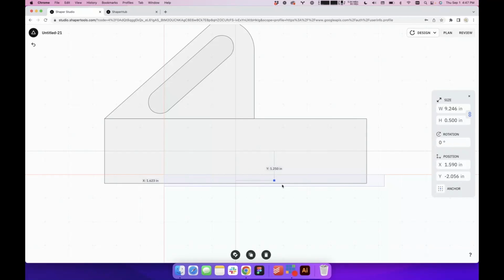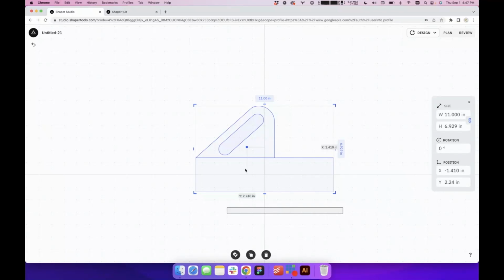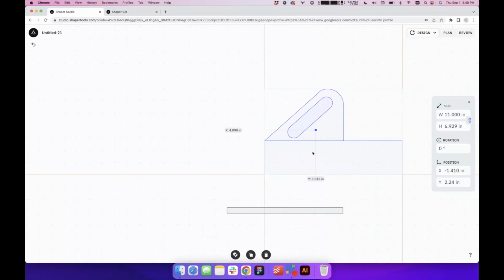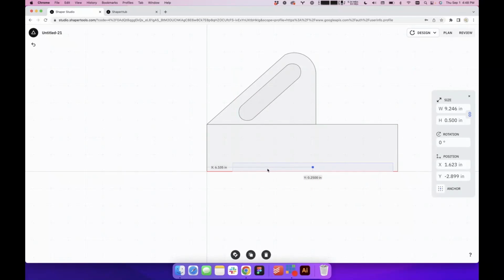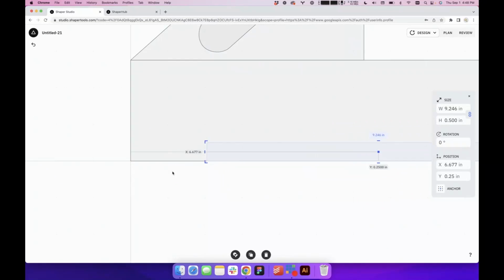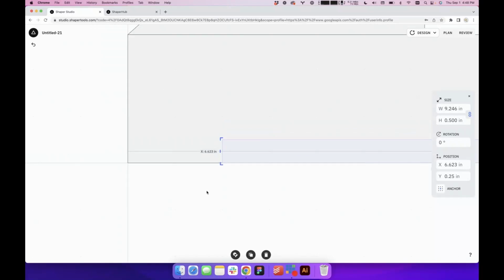Let's do this. I was designing this with everything at 0, 0 as my center, so it's easy for us to do the math. We're just going to move everything and snap it. So the bottom left of that rectangle is at 0, 0. Now we can quickly come in here and snap it to 2 inches from the edge. You can see it's actually snapping to the grid, or I could type this in.